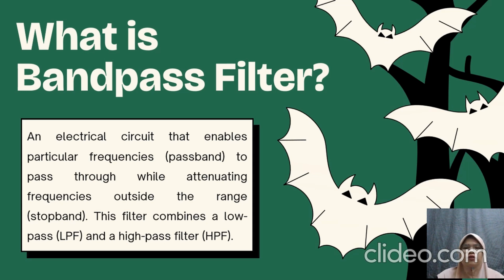The bandwidth of a filter refers to the frequency range where it functions well, often between -3 dB attenuation and the center frequency. The filter bandwidth determines the frequencies it can pass, in fact, the capacity to transmit desirable signals while attenuating unwanted ones. A filter with a bigger bandwidth may pass a wider variety of frequencies.